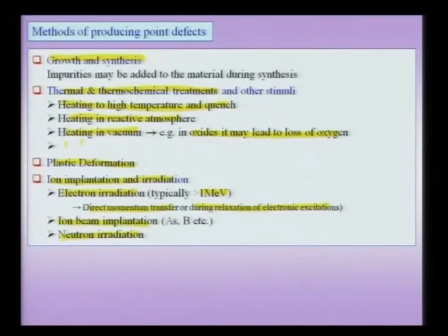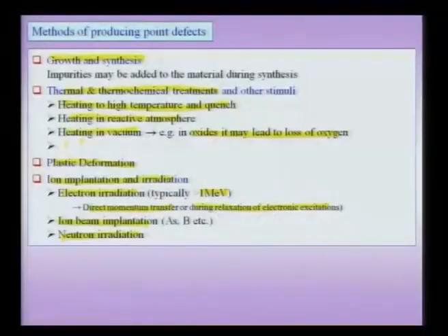and you can produce a large concentration of point defects in the material by irradiating with an ion beam, which would be a heavier version of some of these electron and neutron radiations. So, I have various methods of producing point defects, and having produced them, I can use an experiment like a measurement of conductivity to confirm that you have produced a higher concentration of point defects.